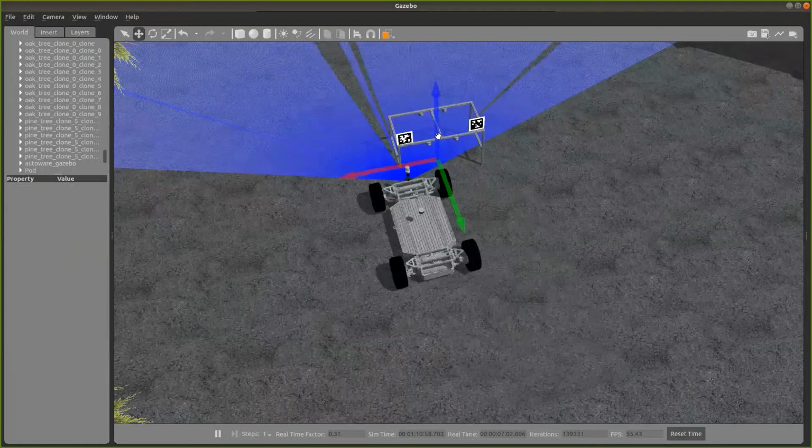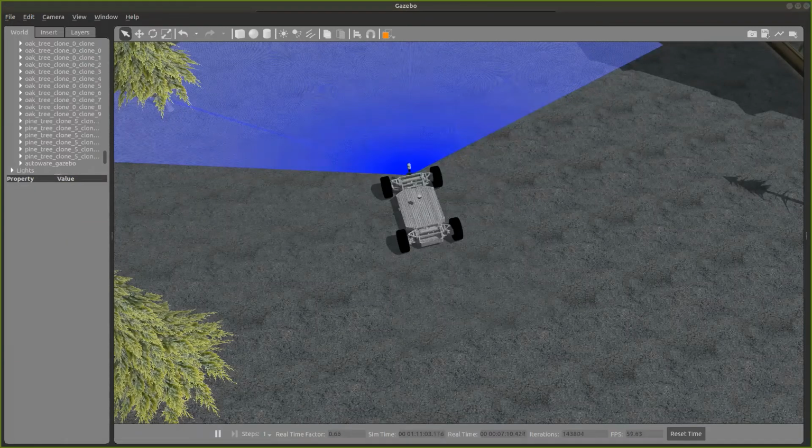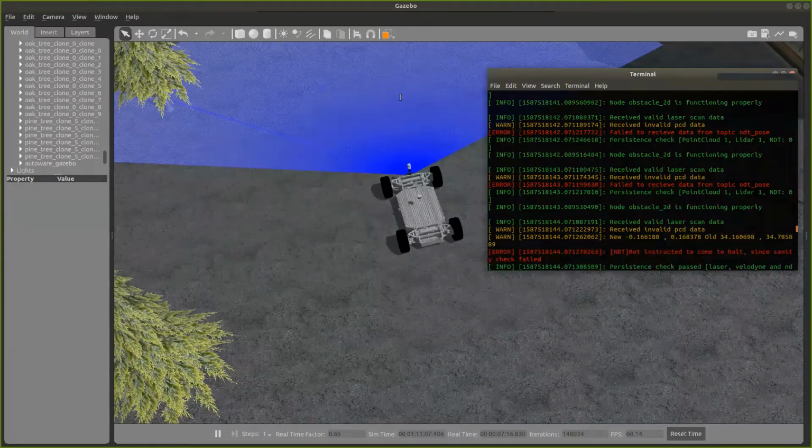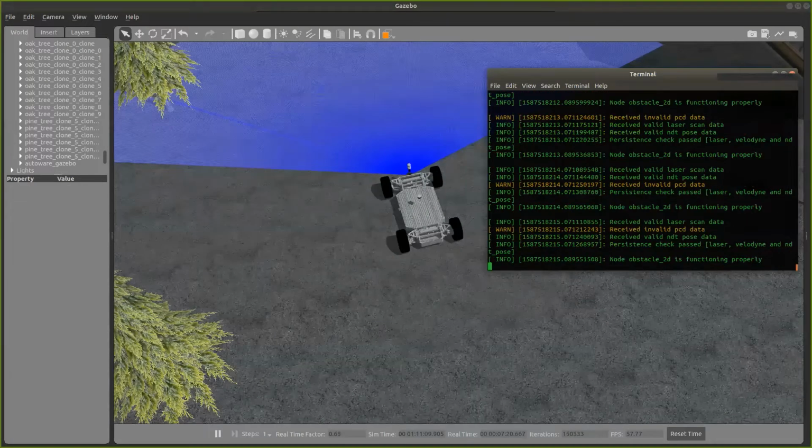For our next test, we will publish incorrect LiDAR data to the scan topic. The expected outcome is that the sanity check in the HMS detects that incorrect data is being published. This data actually consists of negative values.